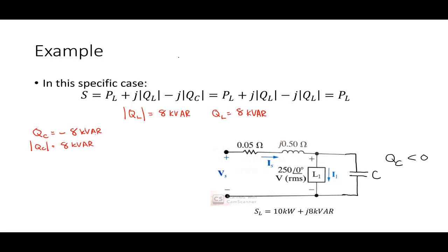So there's two ways of looking at this. The critical relationship that helps us, if we go back to the summary table for all of our power relationships, is that reactive power, which we know is always VI sine of phi_z, can be written as V squared over the imaginary part of an impedance.